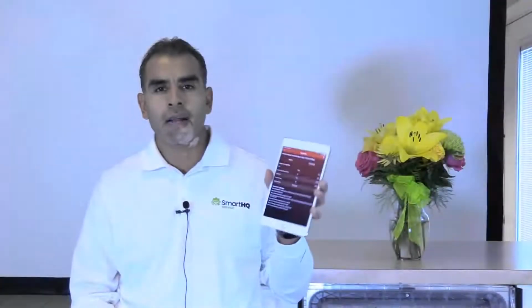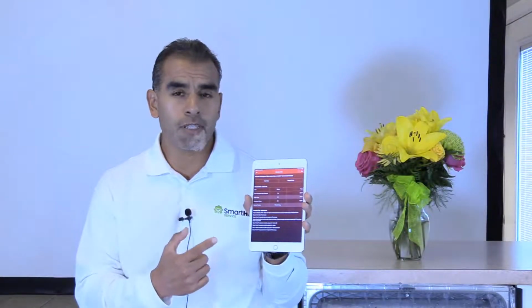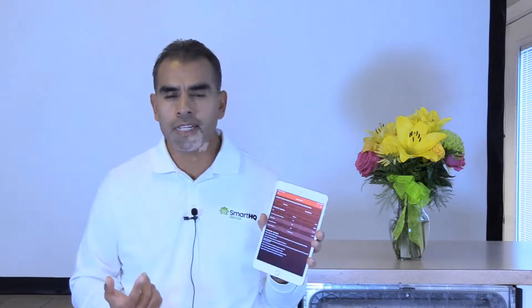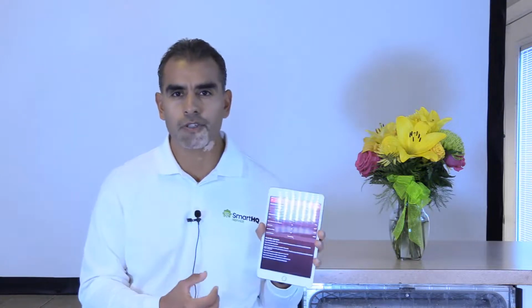All right. So again, my friends, very powerful tool. This circulate test was able to tell me that this dishwasher, for all intents and purposes, should be cleaning the dishes totally fine. Okay. So if the dishes aren't coming out clean at this point, it could be, again, related to how the customer is loading their dishwasher, not using rinse aid, using the wrong detergent, or too much of it, things like that. Right. So you'll be able to explain this to your customers. But at the very least, you know that the product is functioning to perfection.